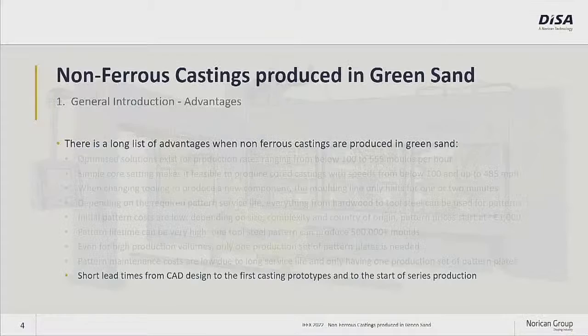Furthermore, as the tooling normally is quite simple, the lead time from a 3D CAD model to the first prototype can be very short, and of course also the lead time to the start of production can be very short too. If we need to do modifications, optimize the gating systems or feeders, it's also very easily done on a pattern for green sand molding.